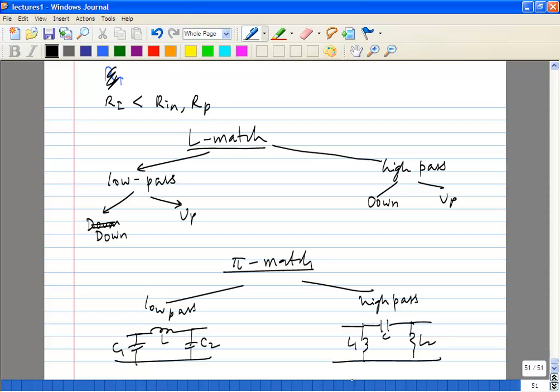The reason is you'll need to make sure each one behaves separately, you'll need to have a certain distance between them, because how do you create inductors? You're going to use some transmission lines on your chip. If they are too close, what happens? You'll have magnetic coupling between them, you'll have interactions between them, right? You don't want that. So usually you will prefer this, but you might find cases where you might want this if your inductance values are small enough, or if you don't worry about area.